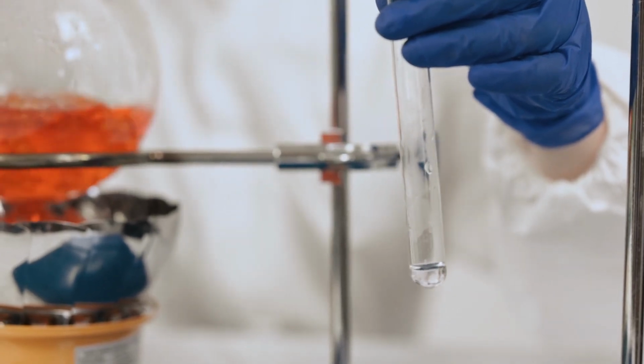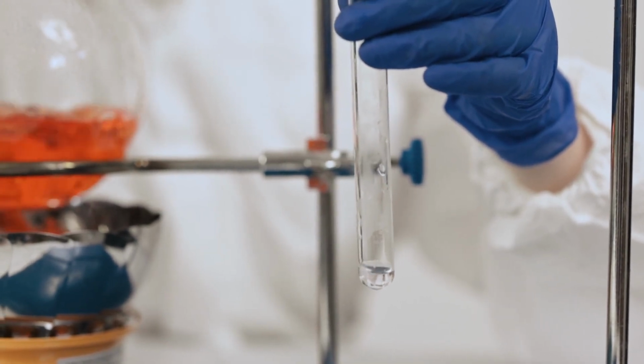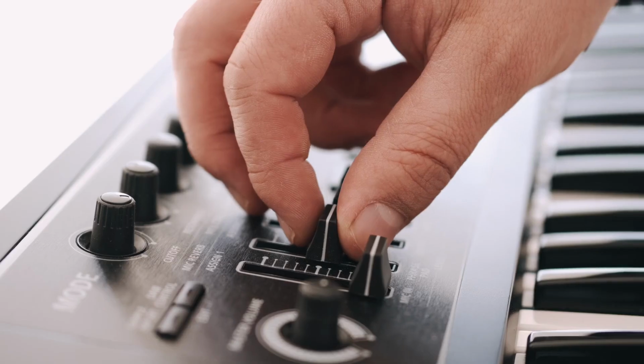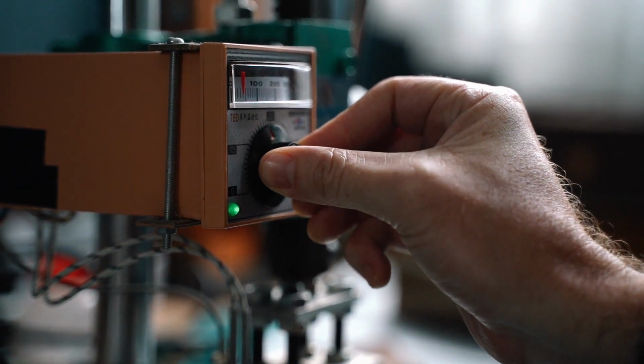Let's conduct a thought experiment to investigate the IV characteristics of different components using a simple circuit with a power supply, an ammeter, a voltmeter, and the component under test. Experiment 1. Resistor, ohmic conductor. 1. Setup. Connect a resistor to the circuit. 2. Measurement. Vary the voltage using the power supply and measure the corresponding current using the ammeter. 3. Observation. Plot the voltage against the current. The result is a straight line through the origin, indicating a constant resistance.